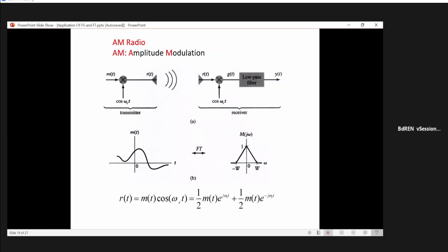So you see how the multiplication operation comes into being. If we have a signal m(t), this is your message signal. Your message signal is actually a finite bandwidth signal. Consider that this is your message signal. If we Fourier analyze it, this can be the spectrum of your message signal. It is certainly a band limited signal, so a finite bandwidth is there. And that frequency, for example, is at a low frequency. The energy of your message signal is also very low.